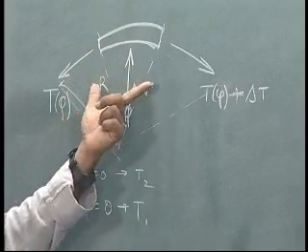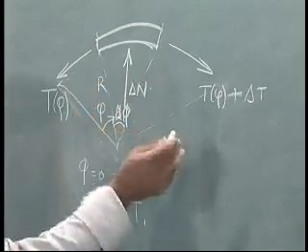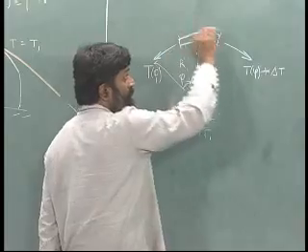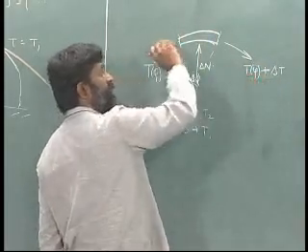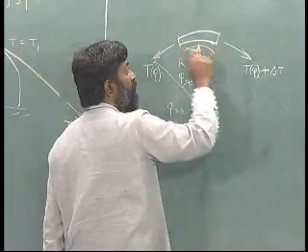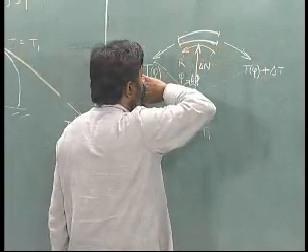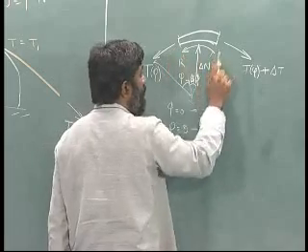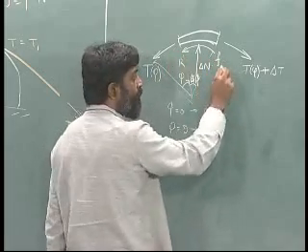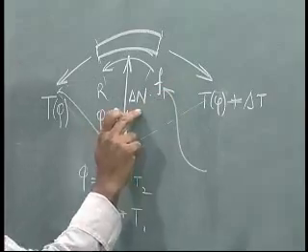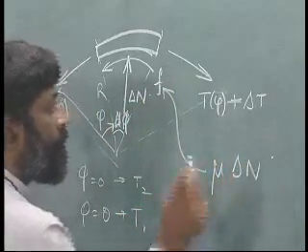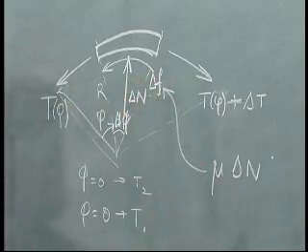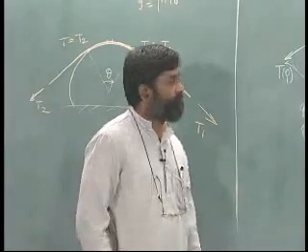Now, what else is missing? There is a frictional force that is resisting movement in this direction. So, the movement is like this. What should be the direction of the frictional force? It should be resisting, which means the frictional force is like this, equal to F. Since it is an impending motion, I know F is related to delta N by mu times delta N. So, let me call it delta F so that it makes sense, okay.